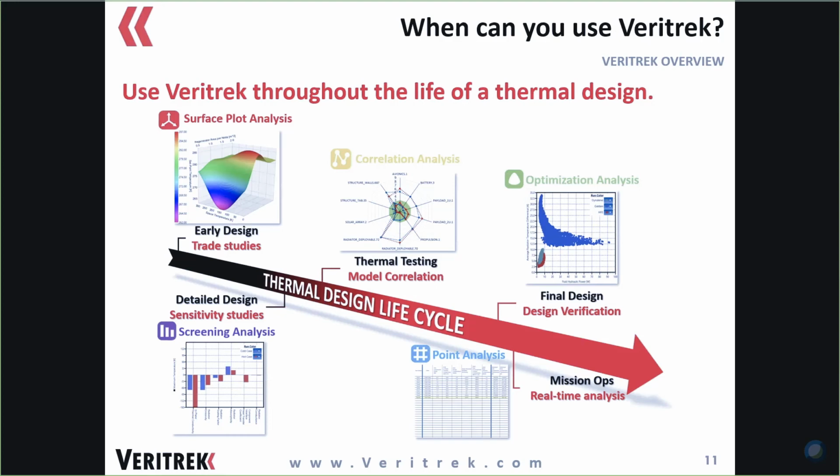The typical thermal model correlation is something that's kind of a guess and check approach. It's very time consuming. And so that's why we're building up this correlation analysis feature to help out with rapid model correlation. And then also late in the design life, we've had users use it for final design verification. So kind of a final check to all the combinations of input factors. Do they all meet our requirements? And so it's a quick way of evaluating whether or not we meet our design requirements.